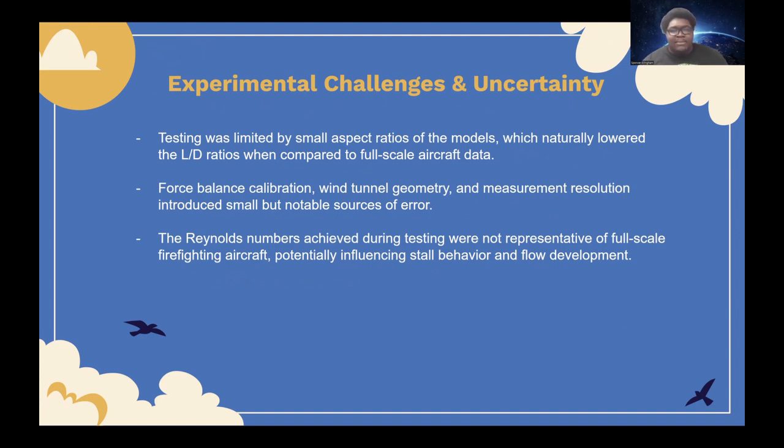Force balance, calibration, wind tunnel geometry, and measurement resolution introduced small but notable sources of error. The Reynolds numbers achieved during testing were not representative of a full-scale firefighting aircraft, potentially influencing stall behavior and flow development.